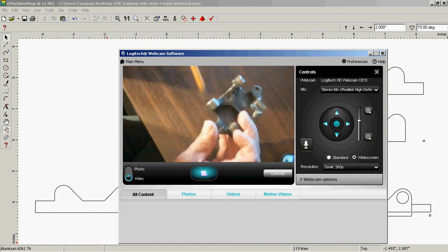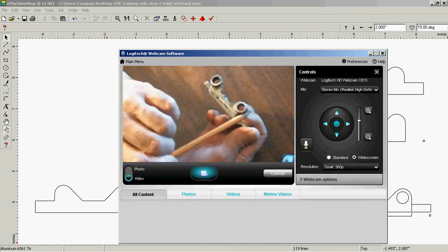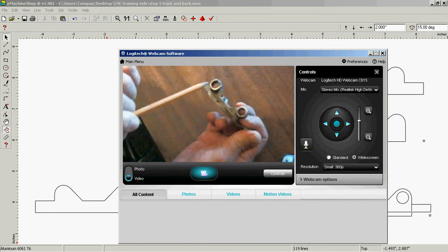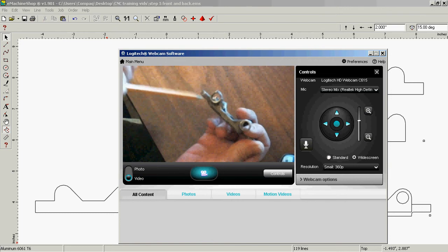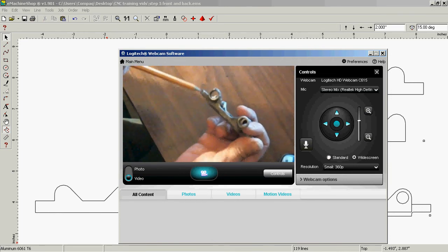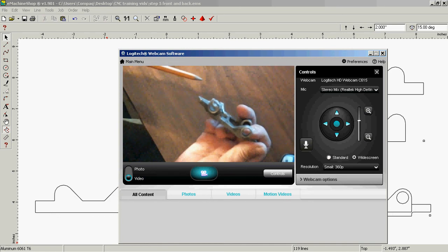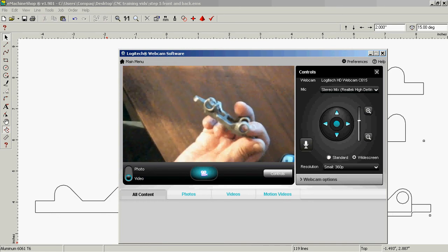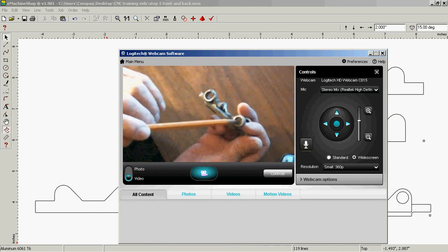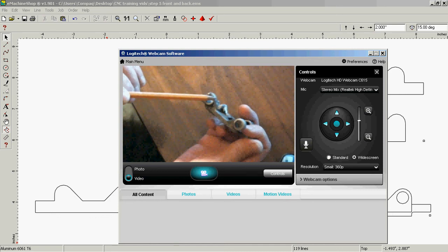So this is the outline I need. I don't need the legs on it on the front view sticking out here. I'll never get to that depth. I just need to keep the little square down in the corner to keep it lined up. So the first thing I'll do is draw the little square in the corner. And then I'm going to copy this section out of that drawing we've just brought over. And then we'll go from there.